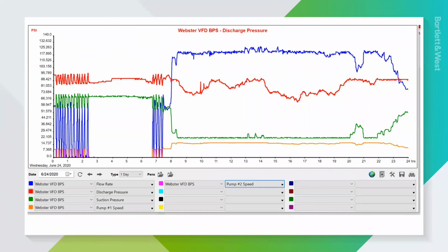Once we saw this, we learned a few things. One thing we learned, if you look at the green line, you notice that it flatlines after about hour 8. And really what that told us was that the water supply to this booster pump station was also dropping. In order to maintain minimum pressures, so those upstream customers had proper and adequate pressure, this pump station was getting choked off, if you will, and didn't have the pressure it needed to keep up with the demands.